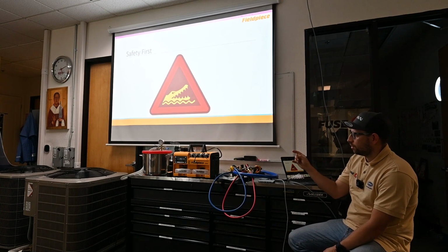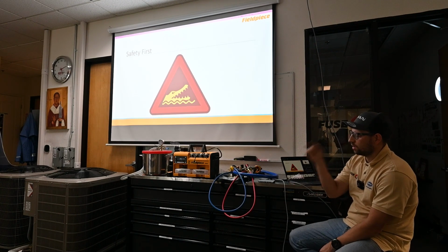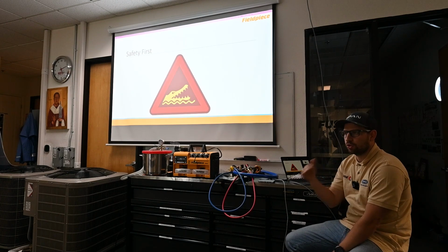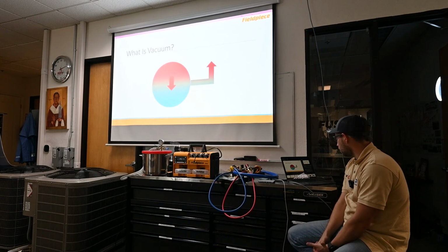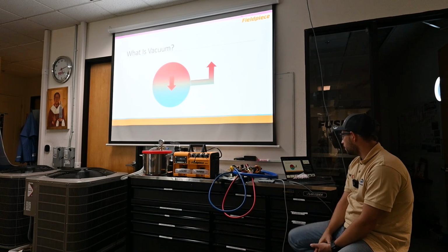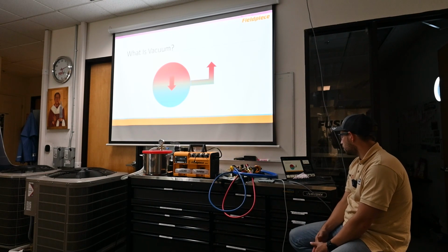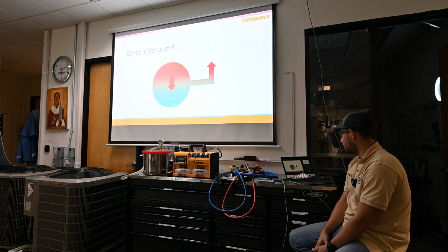Before you start doing any vacuum process, make sure the systems, I mean the condenser coil, condenser unit, don't have any pressure. As pressure is zero. What is vacuum? In the HVAC and refrigeration industry, vacuum is the process of reducing pressure in the refrigerant systems to a specific pressure that is below atmospheric pressure. The industry often refers to vacuum as pulling a vacuum or evacuation.